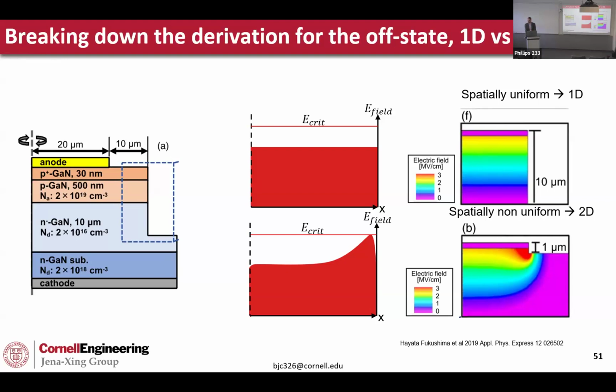And these technologies, are they specific to the materials? For example, gallium nitride has a kind of high symmetry. So the quality of the edges, just when you etch, will be different for different orientations of gallium oxide versus gallium nitride. It will depend, and this is where the predictive limits become a bit more annoying, because for gallium oxide there's a bunch of different surface planes.